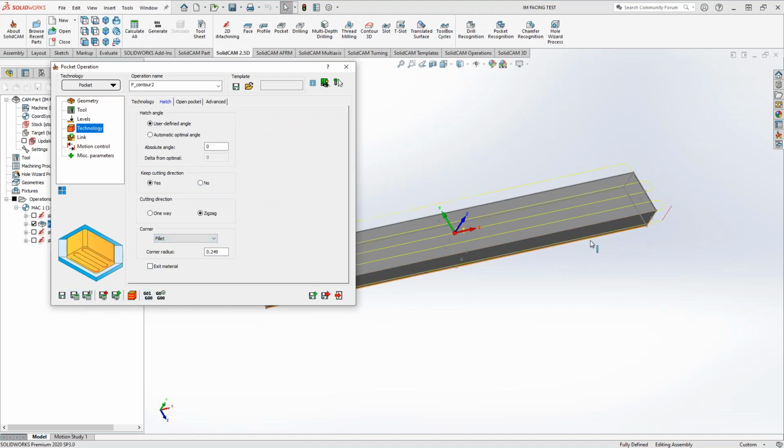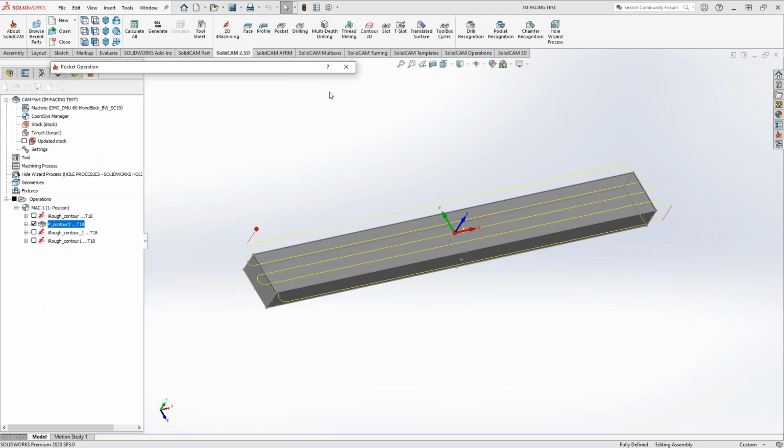Now this will kind of get you up to maybe more of the path that you're looking for. It's coming in there doing a nice little zigzag with the radiuses in there as well. But it's not iMachining, so you would have to calculate those feeds and speeds yourself. That leads into a really common discussion we always have. Because this is only doing the first 25 thou of that part, would you agree, Kevin, that pocketing would be the better toolpath for that? It's only 25 thou.